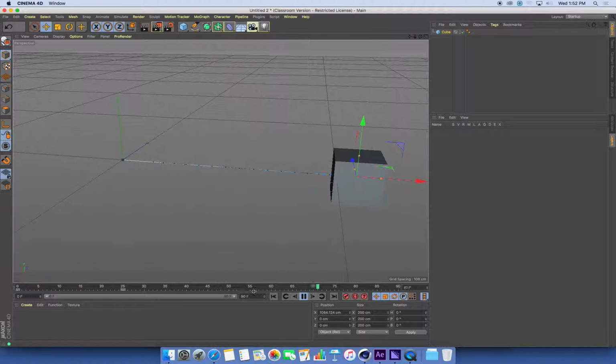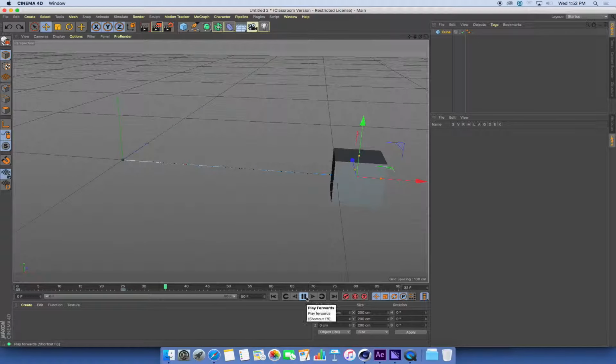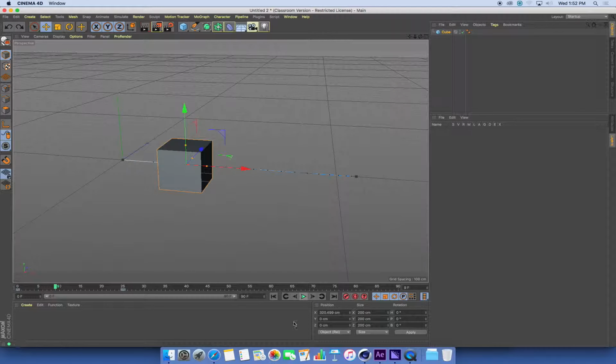Now when we've set some keyframes to produce some animation, if I select this object, I can see on my timeline I've got some little dashes underneath my frame numbers, and those represent the keyframes that this object has. I can retime these if I want to by clicking and dragging these around. It's a little fiddly though, and it would be nice if there's a much simpler, more visual way to shift these keyframes, and there is. This is something I don't think that we've looked at yet. We've set the keyframes, we want to change the timing.